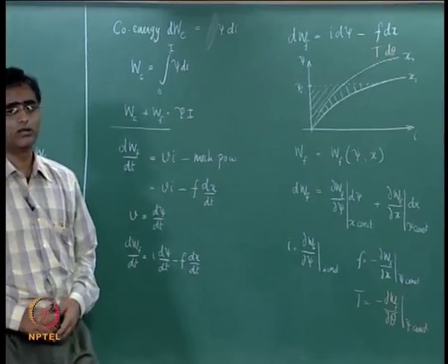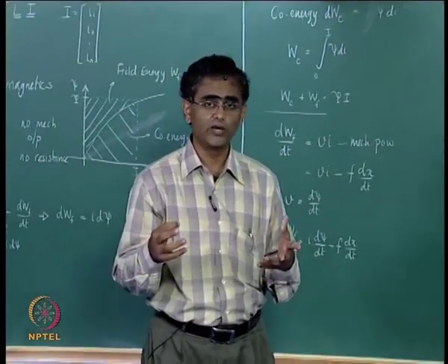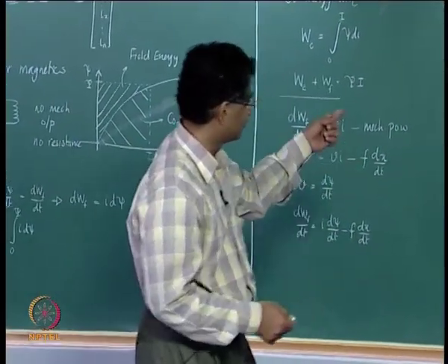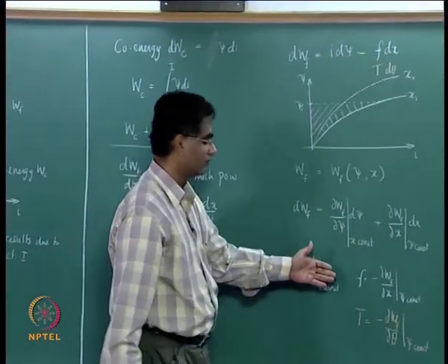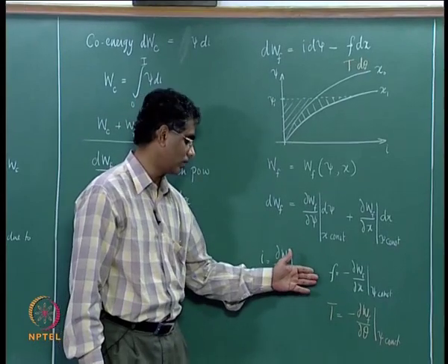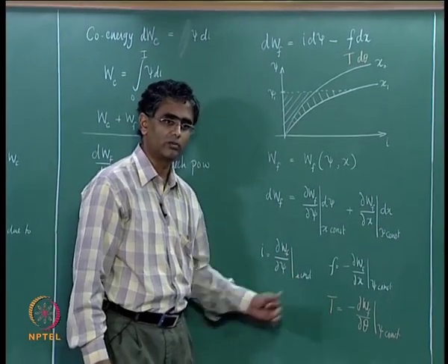In this manner, if you have an expression for field energy in terms of the two variables psi and x, one can find out how much force is going to be developed or how much torque is going to be developed.